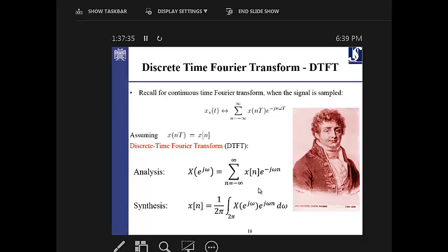So the value of the signal times this basis will give you the Fourier analysis of the signal, or the frequency analysis of the signal, and the frequency parameter is nothing but this omega. The minimum frequency for this omega is 0 or 2 pi, and the highest frequency is pi. That's the analysis. It means that when you want to see the signal of the time domain in the frequency domain, you're analyzing the signal with this formula actually. But the reverse is also possible, because this Fourier transform is a lossless transform. It means that it's completely reversible. So the synthesis form also comes like this.